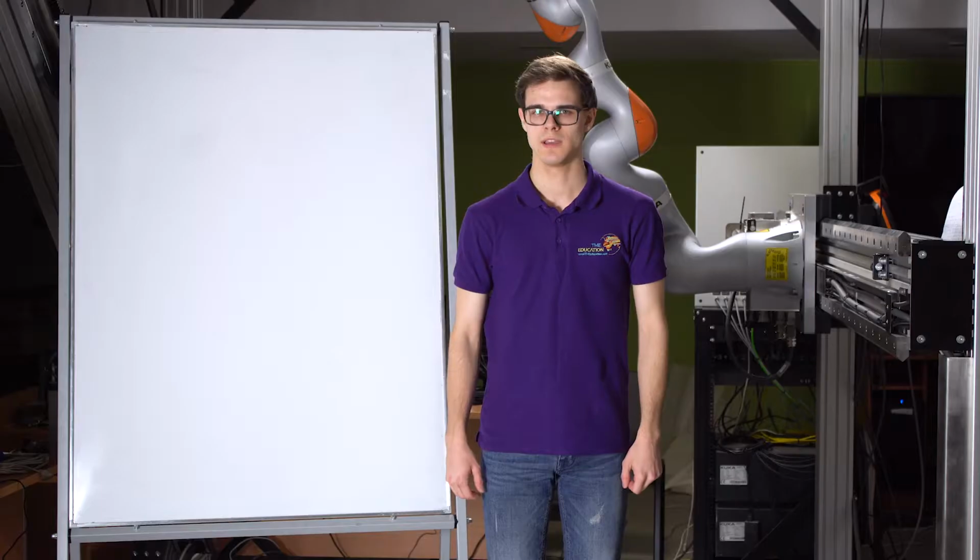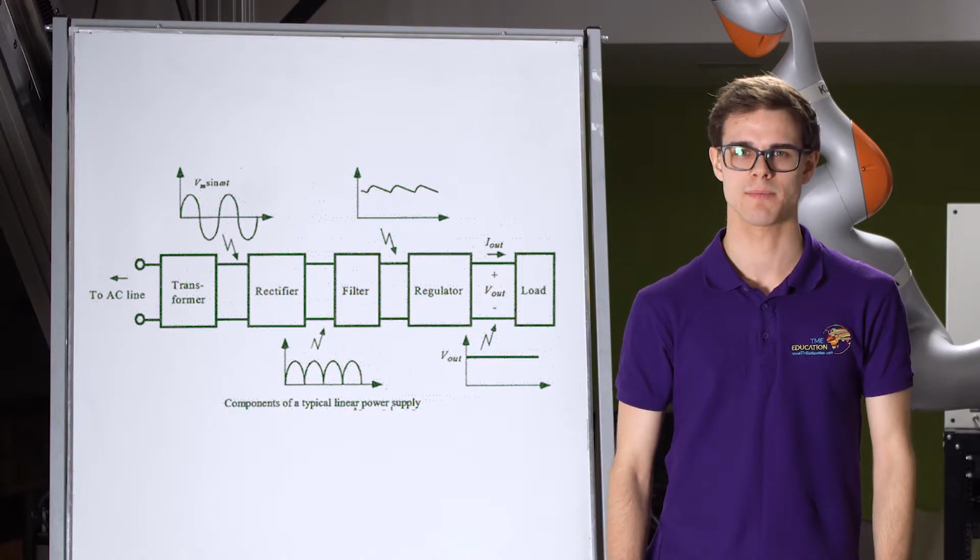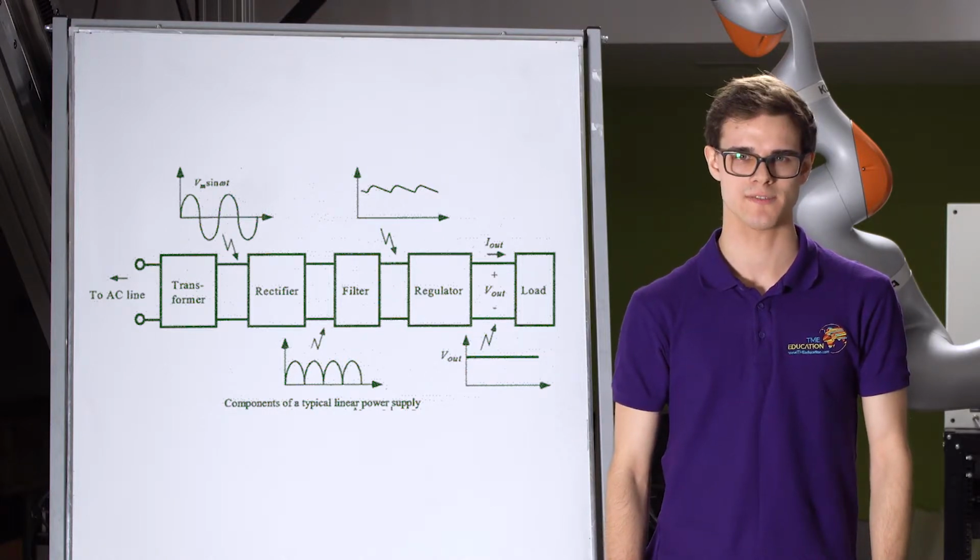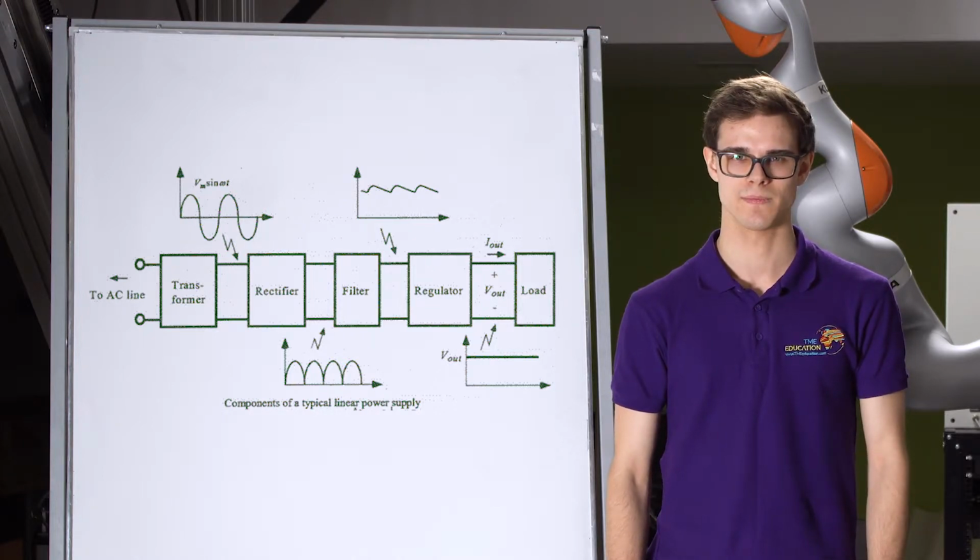Power supplies can be divided into 2 groups in terms of internal design. There are linear power supplies and switched mode power supplies. In both of them, you can separate several main function blocks. In linear power supplies, the first one is transformer, which transforms network voltage to much lower voltage and acts as galvanic separation. The next one is rectifier,